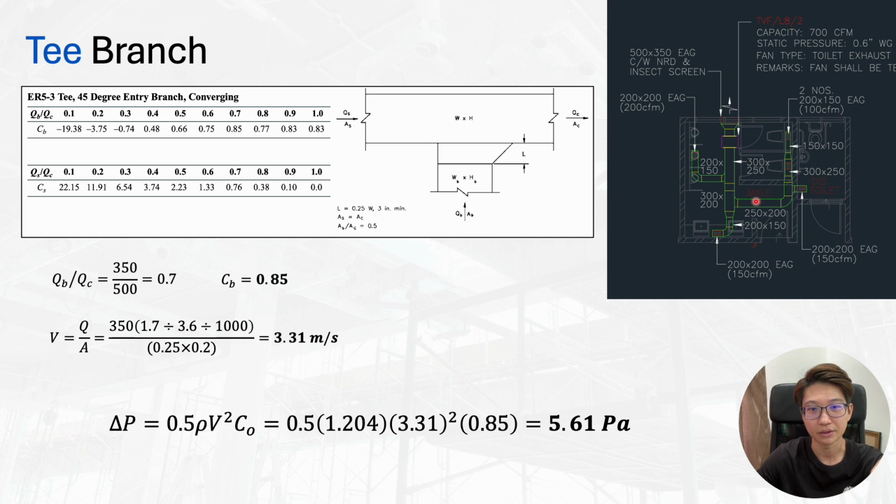You see, our duct is merging into this section, and the diagram they show is this is the main, then this will branch in, right? It's just like our fitting here. This one is going straight, then we branch in. So actually ours is a branch. Just now you said this one is the main, but now we become a branch, we branch in. So we want to look at the branch one. They put B as the branch one, S as the main one.